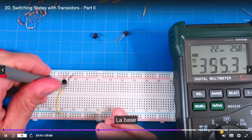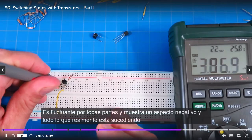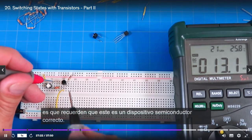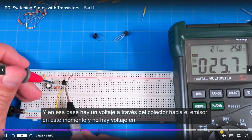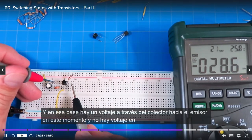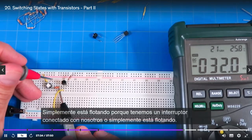The base is at like a nothingness voltage. It's fluctuating all over the place, and it shows a negative and all that. What's really going on is that, remember, this is a semiconductor device. And that base, there's a voltage across the collector to the emitter right now, and there's no voltage on the base. It's just floating because we have the switch connected to it with this resistor.